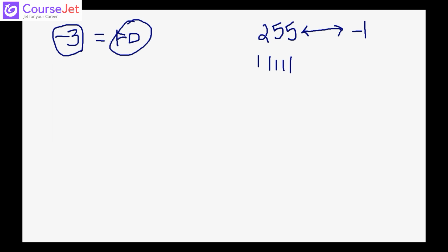So here we will use this FD, which is the value to get the speed of 9600. If you use 9600 and you make the SMOD bit in the PCON register 1, just now I said you have one more register called the PCON register, which is the power control register.